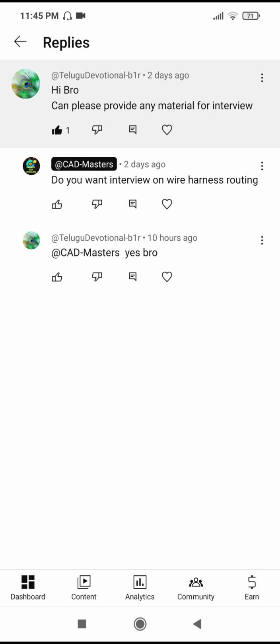So how to select that also, because the selection of heat shrink and calculating the shrinkage ratio also play a required role over there. Then after that, how you calculate the effective gauge, because when a number of wires are being spliced, at that time you have to calculate the effective gauge also, right? So what is the fundamental, what is splice balancing, then which types of splices are used in wire harness.